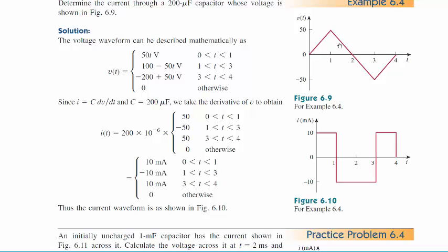I like this problem because yes, you can turn a voltage on or off or switch directions, and so that's realistic to think that the voltage across the capacitor is doing something like that. So then it says, what does the current do? So if you just apply I equals C dV/dt, that's V of t right there, do the little bit of calculus right there, you get the current doing this.